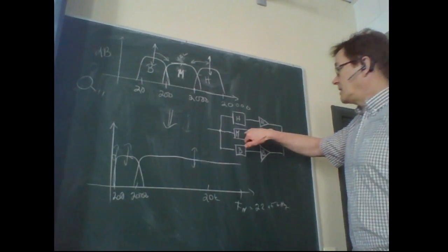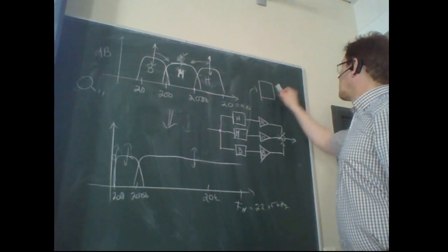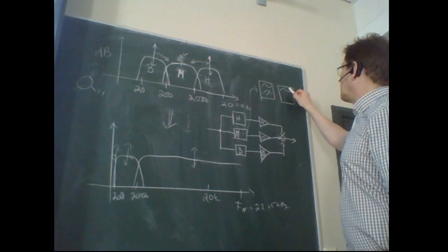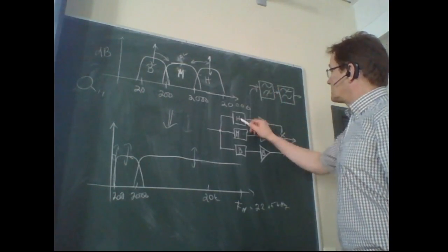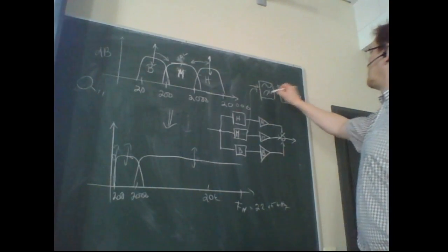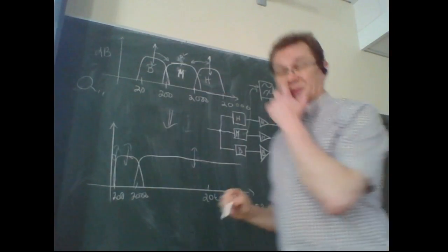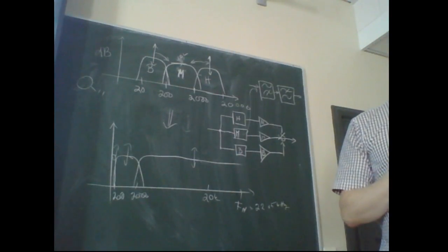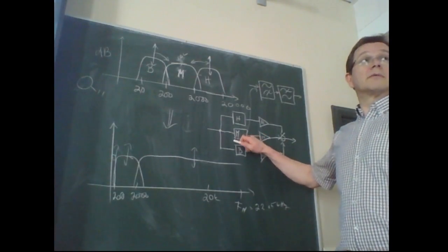So in case of that one, you might consider making it as a cascaded high pass and low pass filter, and just use the output of this filter as the input for that one. Otherwise, you might get a little bit funny results if this one goes haywire on the order number.